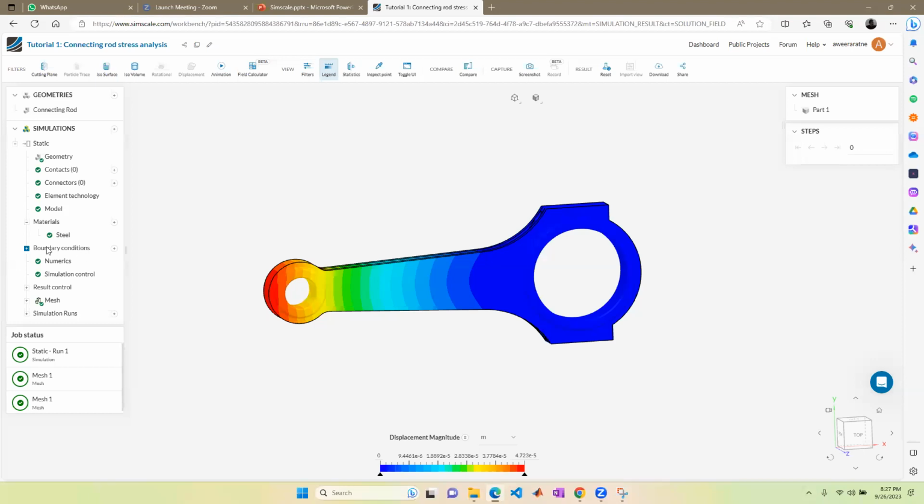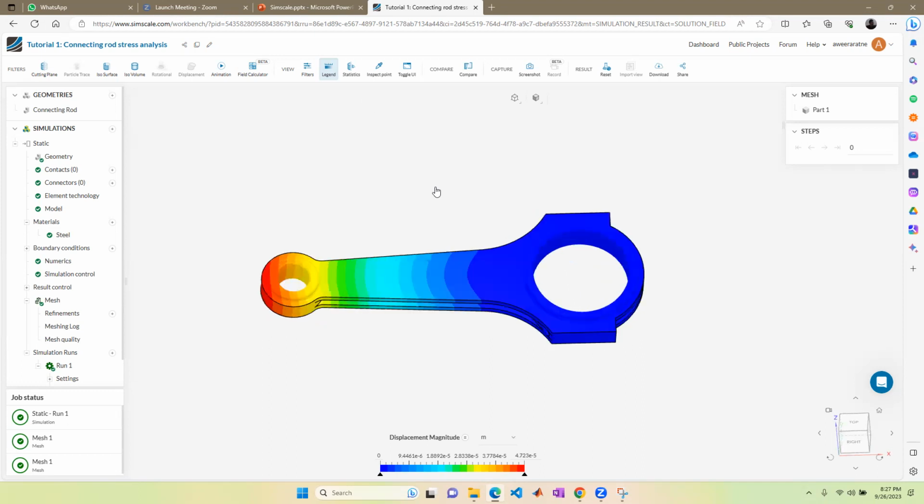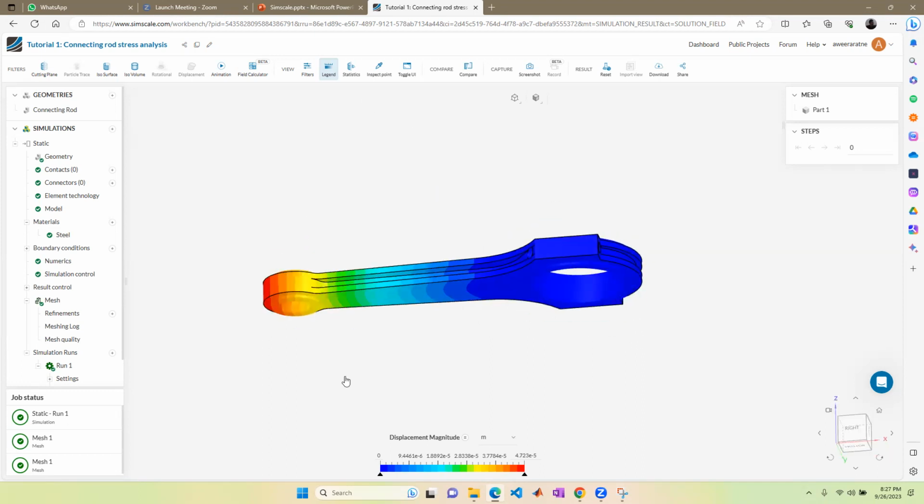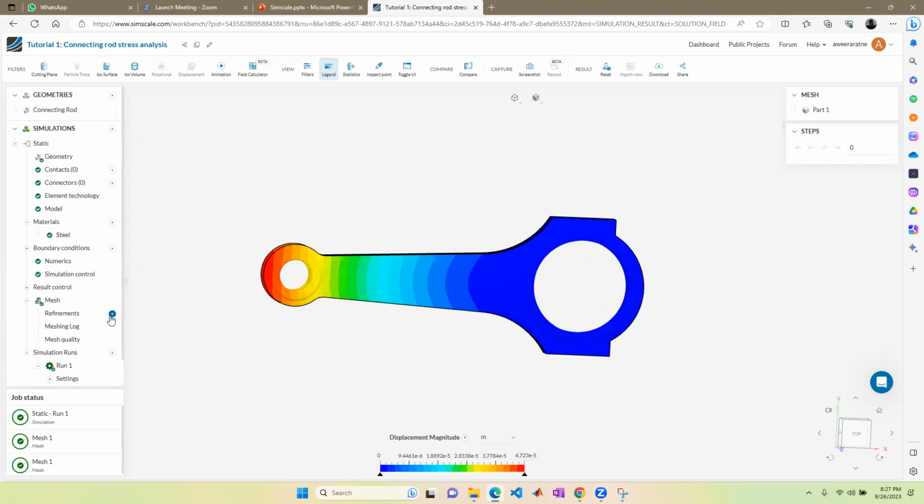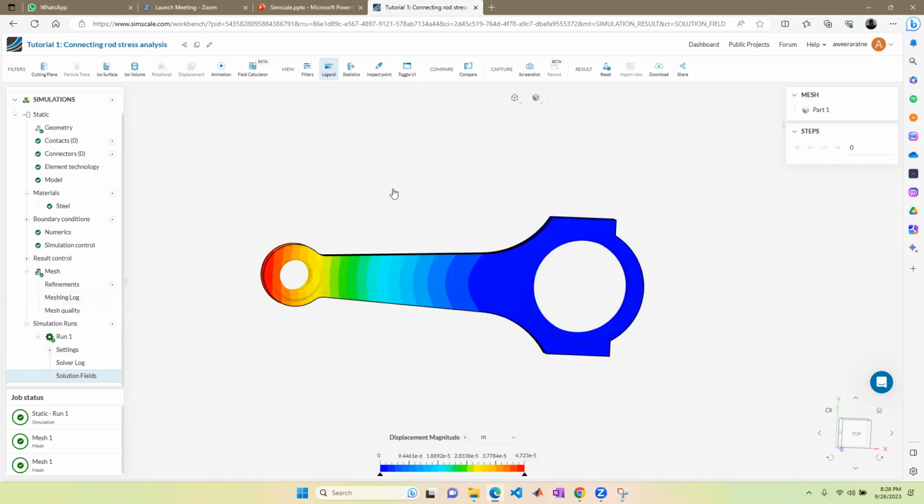After that, you move on to specifying the model parameters and the boundary conditions next. Pay close attention when specifying boundary conditions, and after that, you specify how the mesh should be. Specify mesh requirements if needed, and finally run the simulation. After that, process the results, then go over the result plots carefully, and you will be able to obtain qualitative and quantitative results for the simulation.